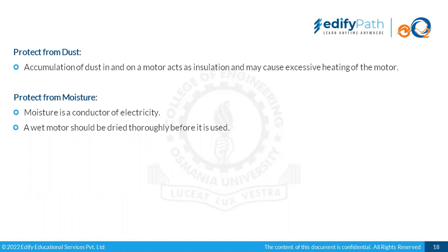So we should ensure that from time to time we are overhauling the motor and protecting it, so that dust doesn't accumulate on the motor, because that would prevent the heat dissipation of the motor and can result in overheating of the motor, and the performance of the motor can be disturbed.